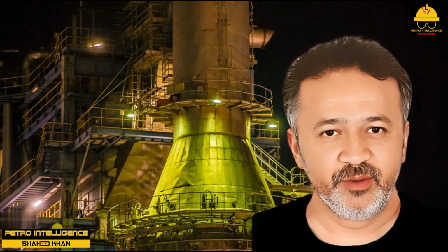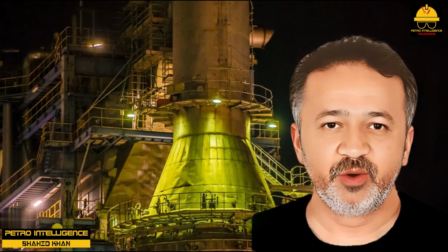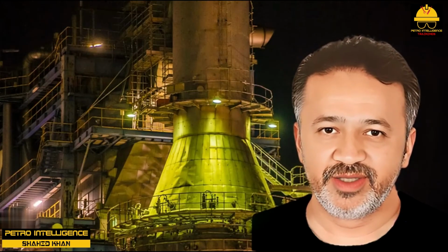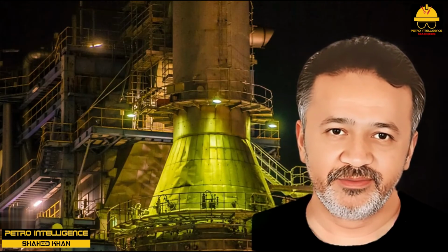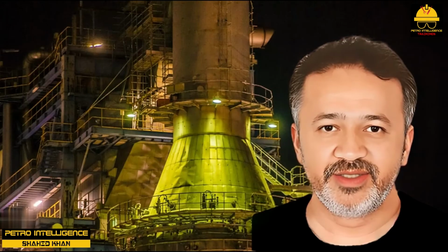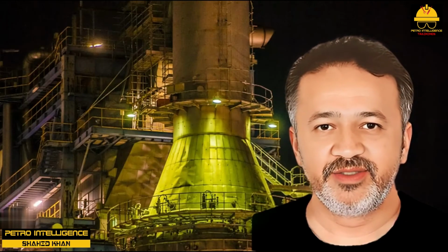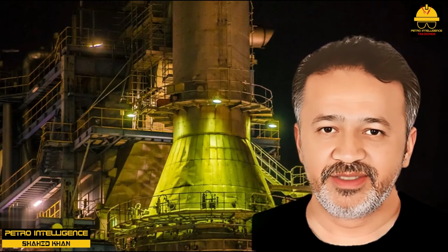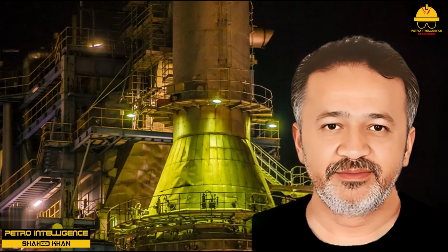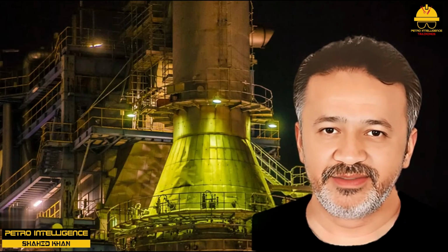However, there is a problem with this target. The problem is wind. Wind can create a variable draft of plus or minus 0.10 inch H2O or more. If the draft decreases as the gusts of wind come and go, then the heater may go positive, and a personnel hazard is created. Thus, the minimum safe draft depends upon the variability of the wind. Not at grade, but the wind speed at the top of the stack.